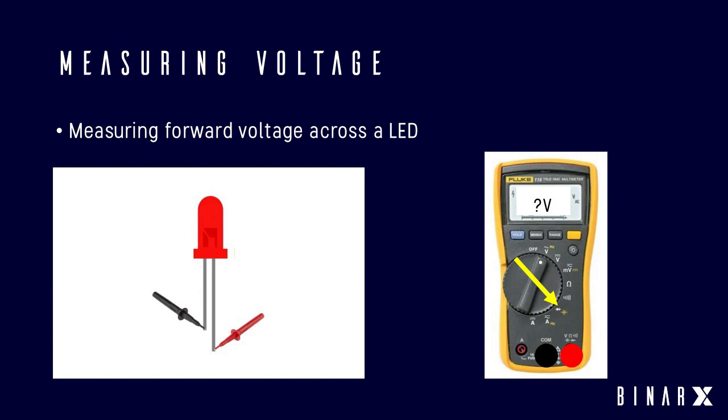We had our LED voltages. We wrote them down. We also determined them through the multimeter. Everyone that's got an LED voltage written down, that is the V in your I equals V over R, and you want to calculate the R. So we're going to rearrange I equals V over R so that we have...